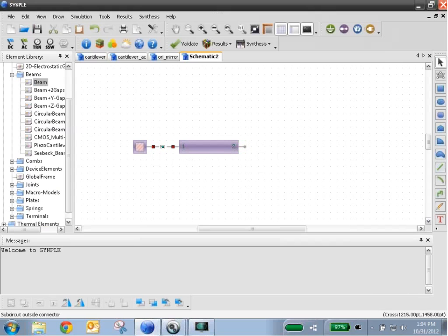And then the most important element that you'll see in many of the designs that you'll make is the multi-domain bus. You can access it by clicking right here, and you can insert this splitter. And you'll notice that all along the right side of it, it has these variables that you can change.